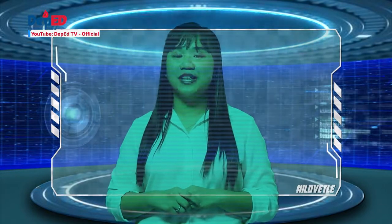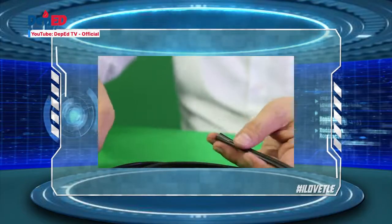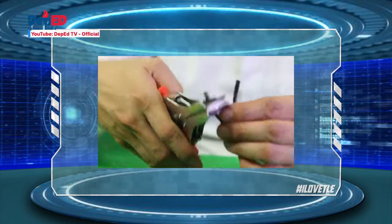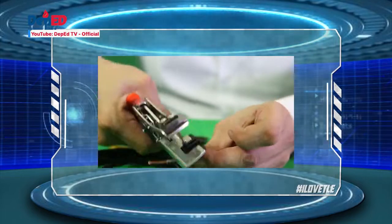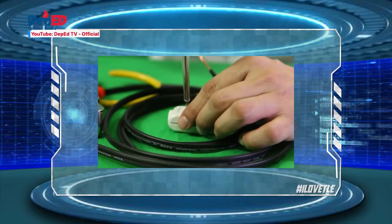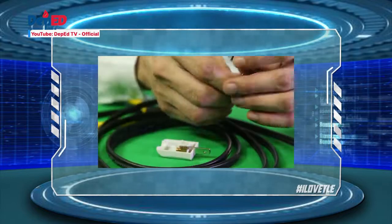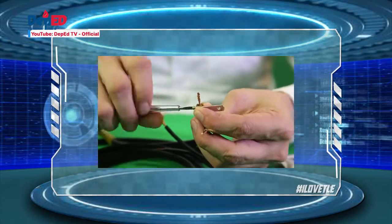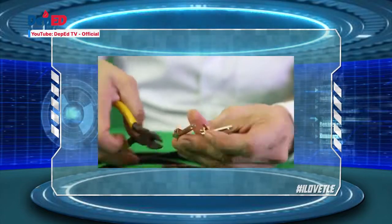Here are the steps in making a 3-meter 2-gang extension cord. Number 1. Split both ends of the flat wire using side cutters and strip off the wire insulator using the wire stripper for about 3/4 of an inch. Number 2. Using a screwdriver, unscrew the male electric plug and open its cover. Number 3. Insert the wire into the male plug. Tighten the screws down to hold the wire securely. Cut the excess wires if needed.